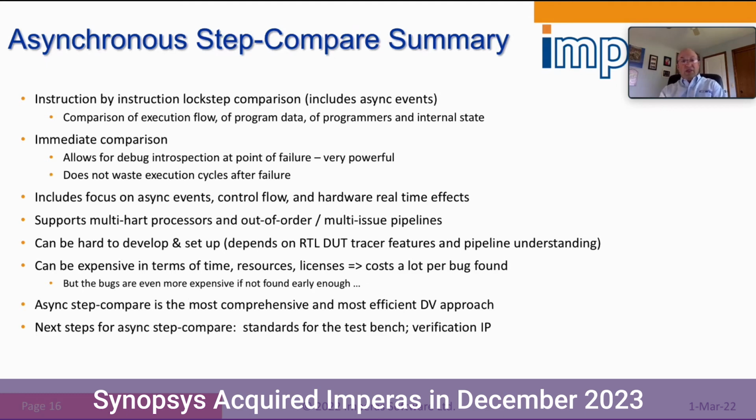So asynchronous step and compare. Instruction by instruction lockstep compare, including asynchronous events. That's what we're talking about here. This is the highest level of processor DV for RISC-V. It allows for immediate comparisons, debug introspection at the point of failure, and doesn't waste execution cycles after the failure.